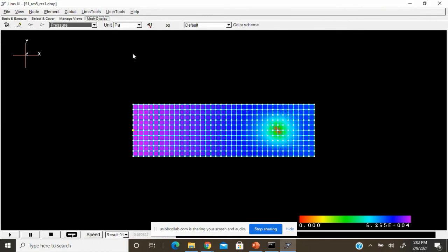You can also visualize the pressure. You can see that at this point you are going to see lower pressure occurring, and you will also be able to see the fill factor and see whether there might be any possibility of voids. Fill factor is essentially how much of the control volume is filled, and the ratio varies from 0 to 1.